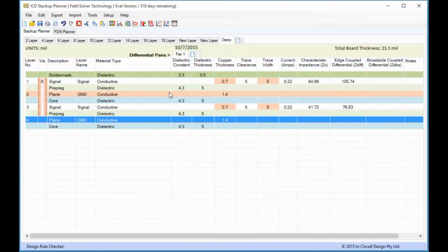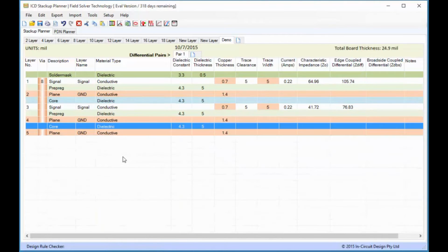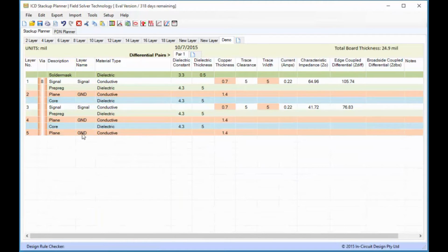So again, we've got core material separated by prepreg, or if it's on the top, we can do something called a copper foil. Once this has been hardened, they can actually etch off the copper foil. It all depends on how the fabricator is going to do this. That's why it's really important that you have a conversation with them, because how you get this stack up together is going to be very dependent on their processes. What I'm going to do on this last one is put a copper here below. It's going to be actually a plain copper. So now I've got half my board done here.